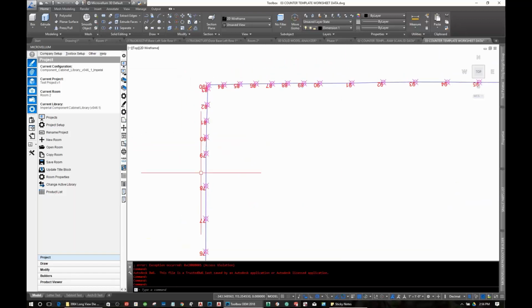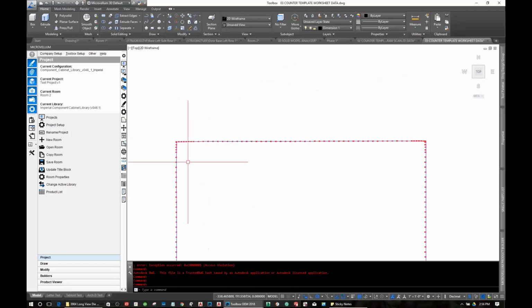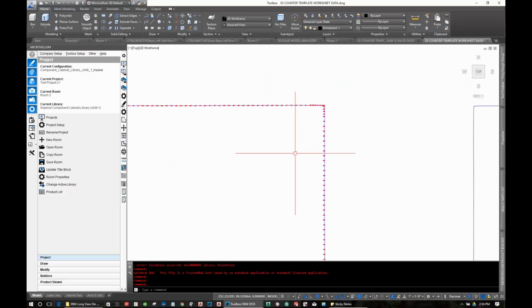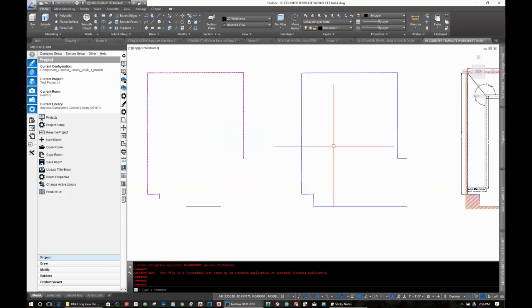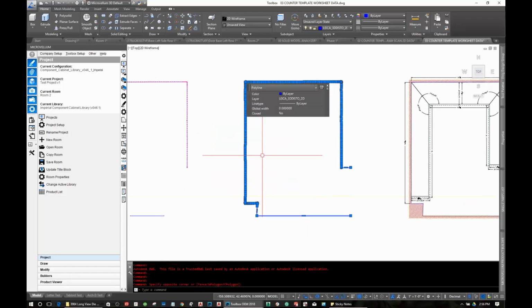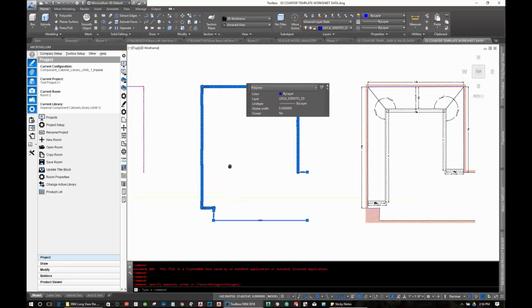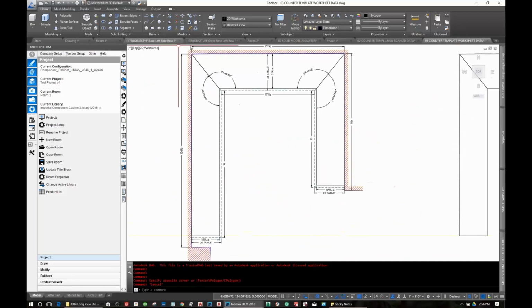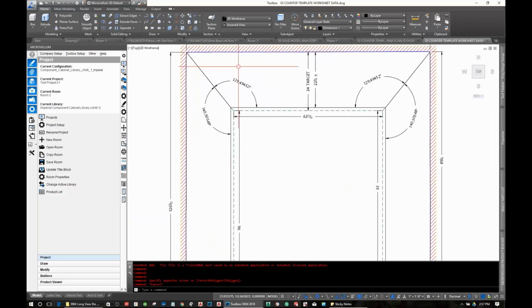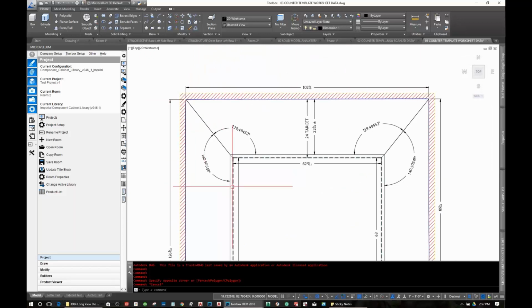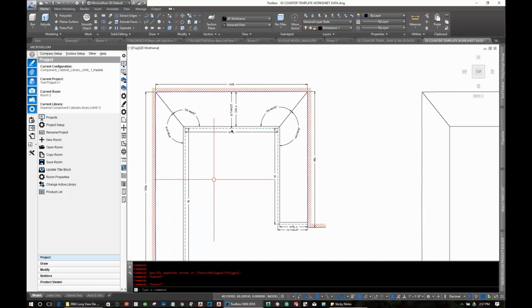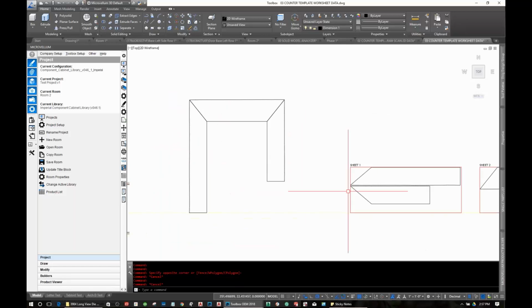So if I were to go in the corner, you can kind of see where the mud joint is. You can kind of see where there's imperfections in the wall. Well, that's the actual wall. That's like if I were to scribe the countertop, that's what you get. So I went through and I made a continuous polyline from that. It's just a 2D polyline. And then from there, I created the drawing that I needed for the countertops. The front half of the countertops are all nice and straight and square, and the back half is all scribed in. And then I isolated the countertops.